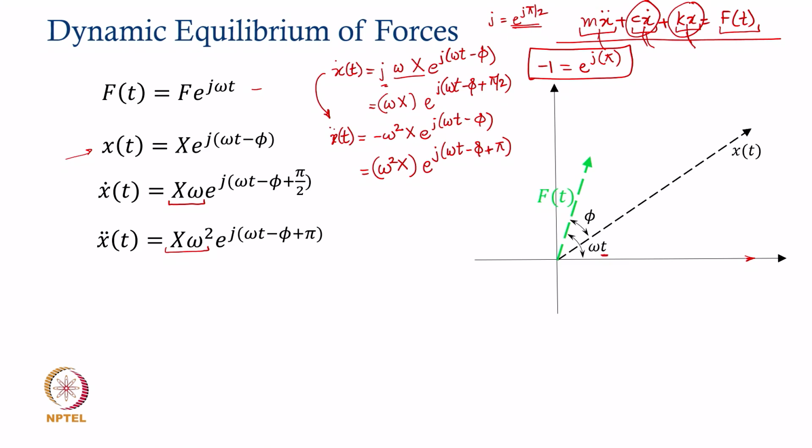So, now if I have to show these forces C x dot and K x, I can represent the restoring force Kx in the same alignment as the response itself, because the restoring force is proportional to the response amplitude. So, at any instant of time Kx is going to be shown the way I am showing it right now. I am going to focus on this governing equation of motion and show these forces.